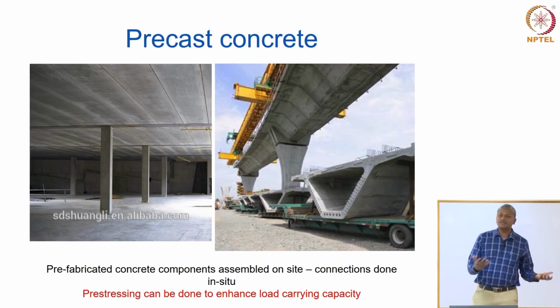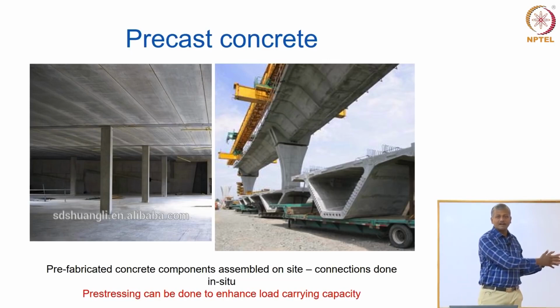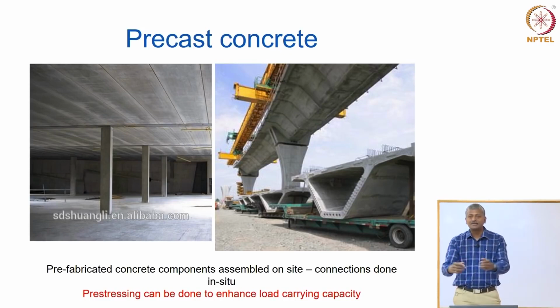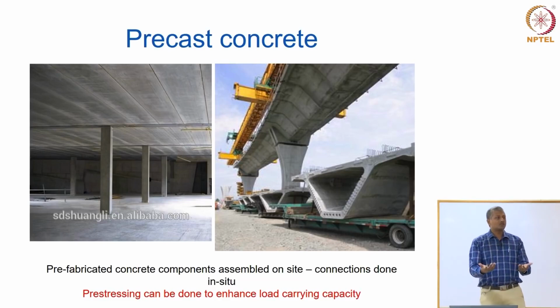Now, what is precasting? That means without really assembling or shaping the concrete on the site, I make the components of concrete in a factory, bring them to the site and simply stitch them together, right? And that's called precast concrete. The obvious advantage I get from precast construction is that now I can control the quality a lot better.